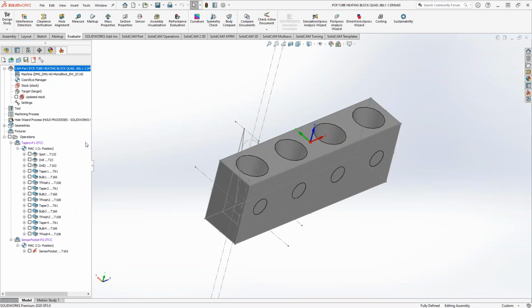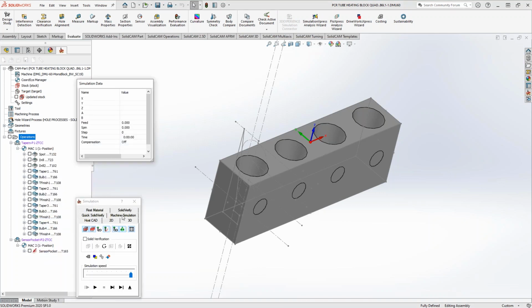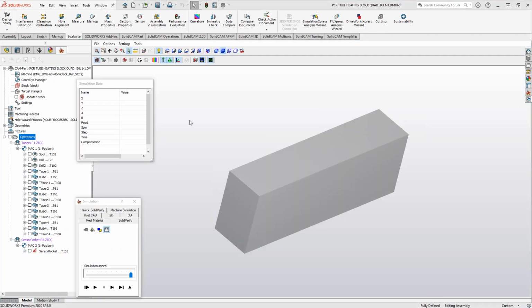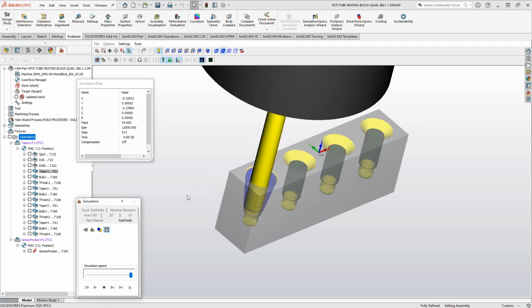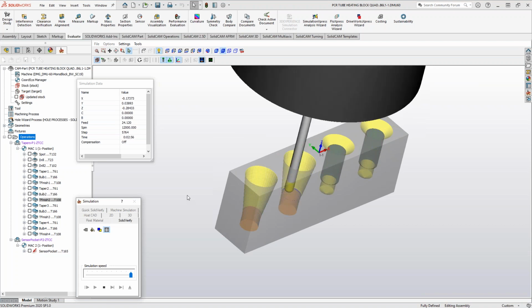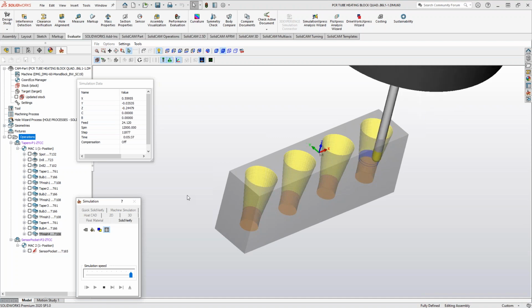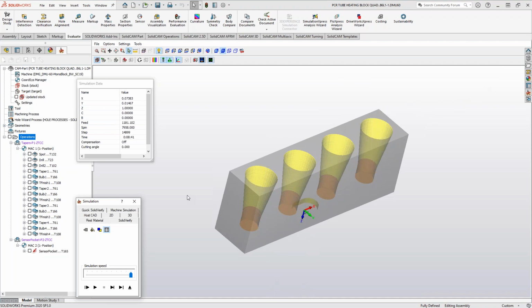So basically, I believe what he's referring to is if you just do a simple simulate in Solid Verify, you have some of these modes that we've covered before. So this is just the, what is this one called? Render mode. And then hybrid is basically just showing it's transparent. And really transparent is the only way to see it internally. Whenever you do any kind of information or toolpath on the inside there, that's really the only way to see it, other than if you were to do mill turn. There are section views in mill turn only because we know exactly where that turning plane is.